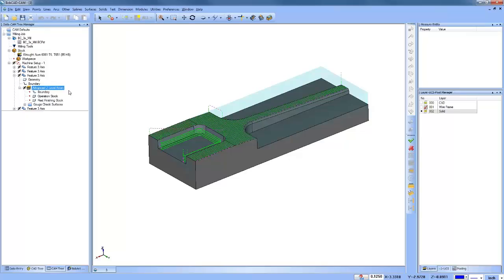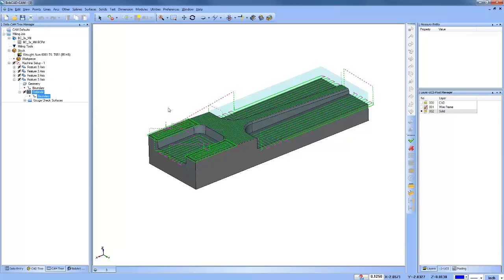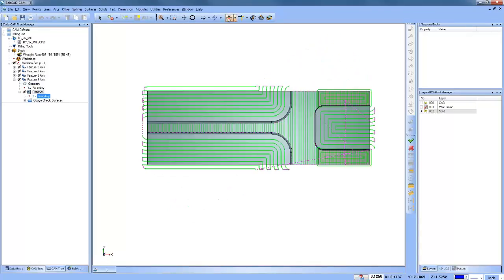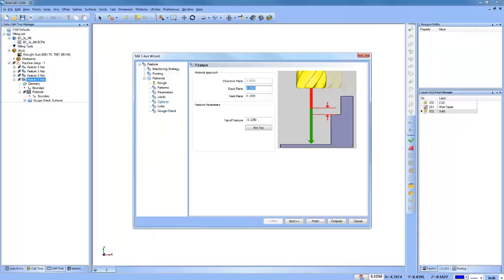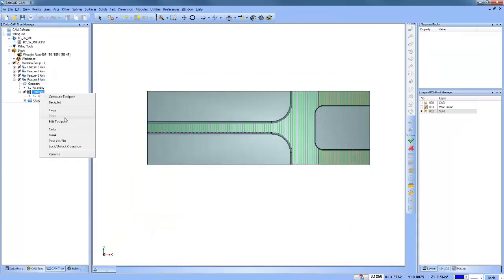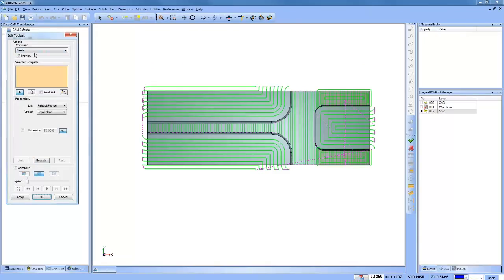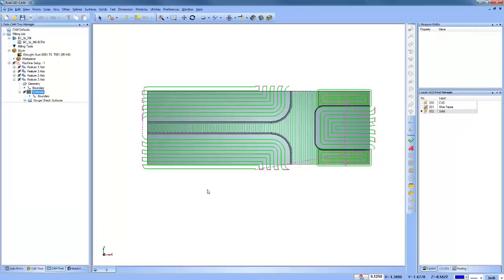All right, sounds good. So again, we have another one here. I have some flatlands that I've done. The extension does work with all the different toolpaths. Let me go in and edit this guy, and we're going to do Extend, Cut. You can see that it extends out further. Now, whether that makes sense or not, I don't know if this is the best toolpath for that, but it does work with all the different toolpaths that are there.